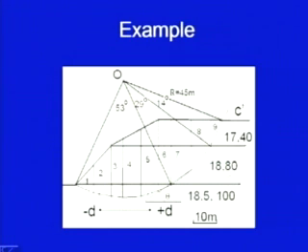We have divided the slope into slices 1, 2, 3, 4, 5, 6, 7, 8, 9. It is as per our convenience, and as discussed last time, for the sake of making the computations simple, I have taken one slice ending here where the profile is ending. Same way one slice should end here. You can have uniform width also.